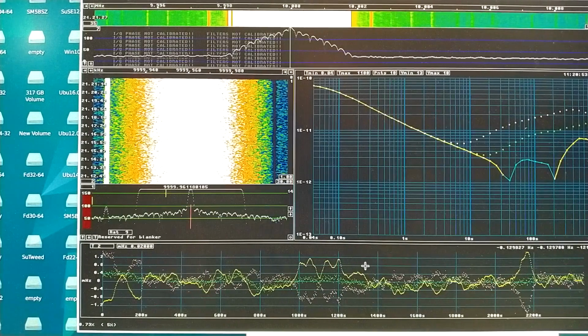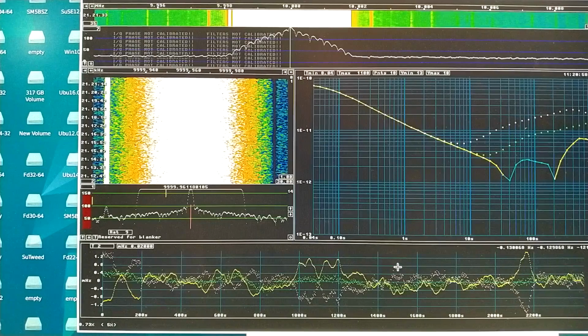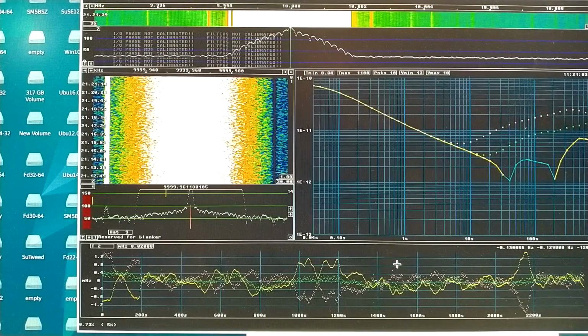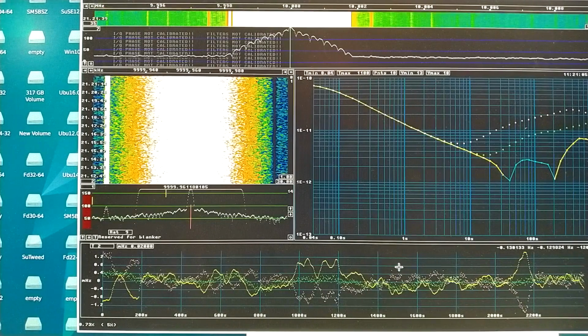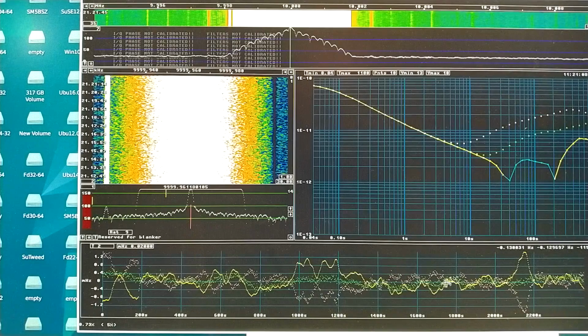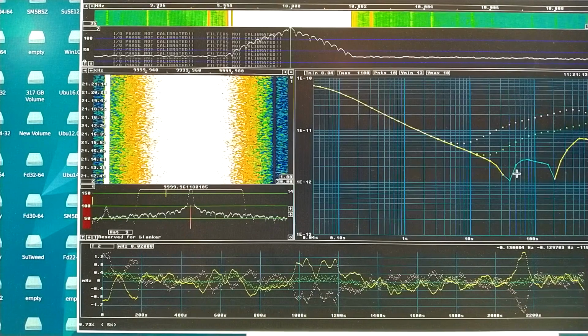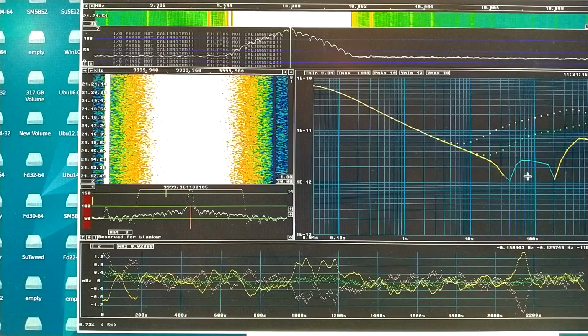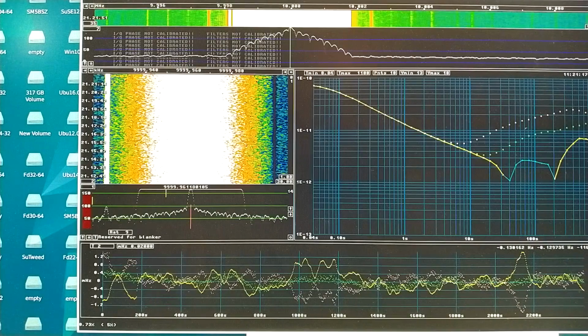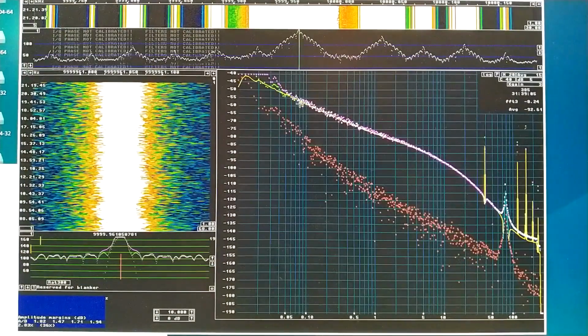The optimum solution for a test system like what I am using now would be to use the rubidium oscillator as a reference for both channels, but with a phase lock time constant in the order of, let's say, 50 seconds, maybe 100, I don't know exactly, because you can see here 0.01 second, I have to shift the scale vertically.